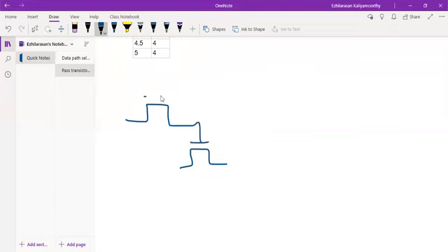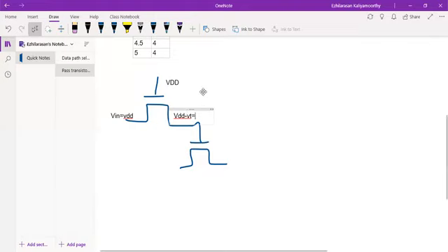Now you see this is our Vin. Assume I'm applying Vin equal to VDD. Here the gate is VDD only. Now, how much will I get here? Actually, I will get VDD minus VT, which is a maximum of 4 volt. So now what is the V out here?